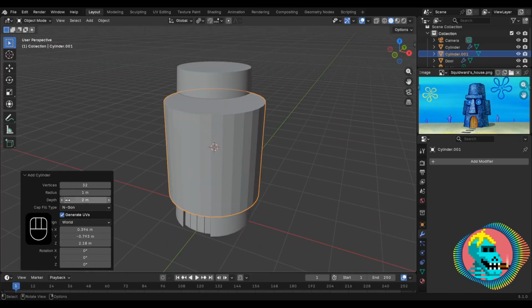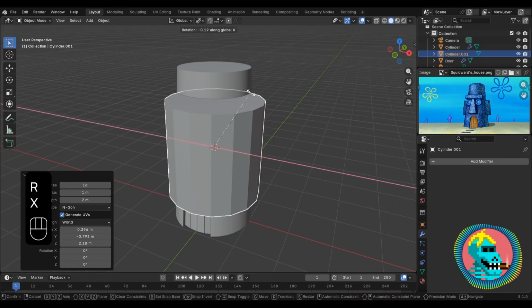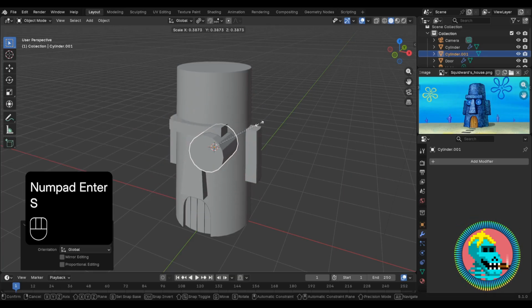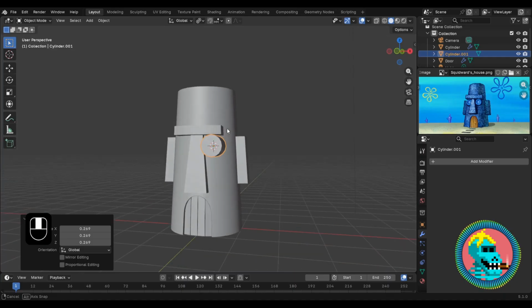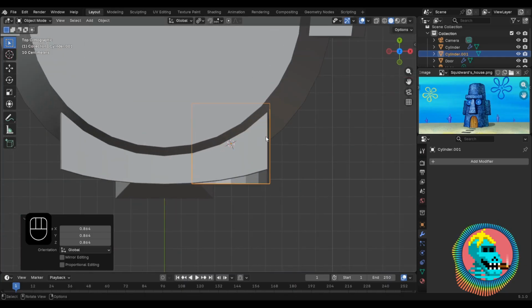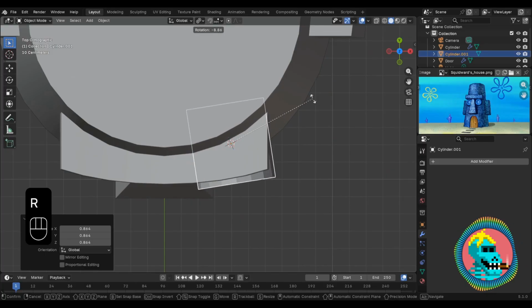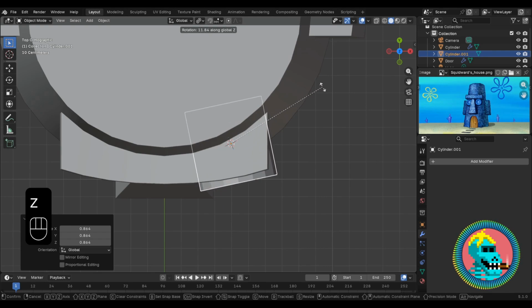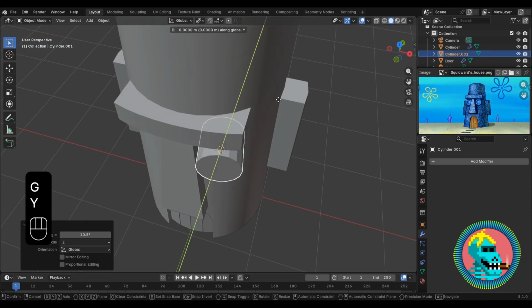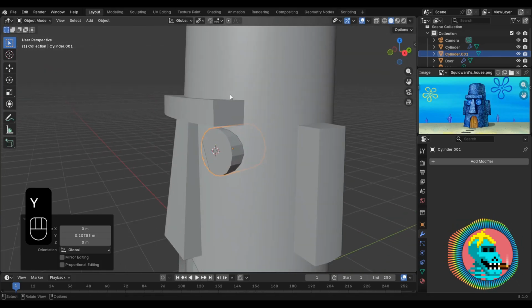Let's go to the Edit mode and set 16 faces for our cylinder. Next, press R and X keys to rotate along the X-axis. Click the scale. Now let's make a small rotation by pressing our rotate key again and locking the Z-axis for rotation. I'll deepen the position a little and turn it a bit more.